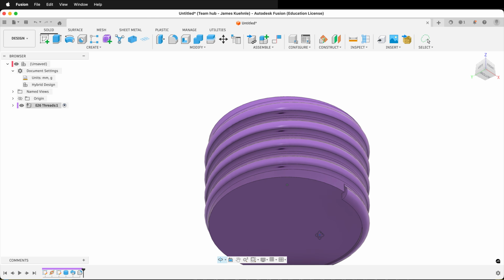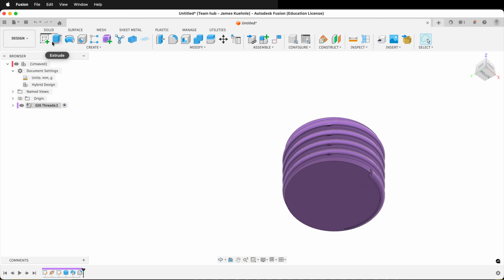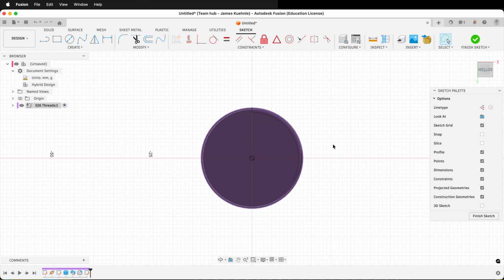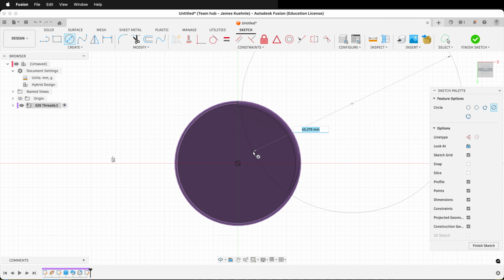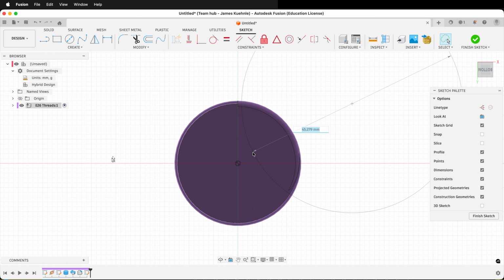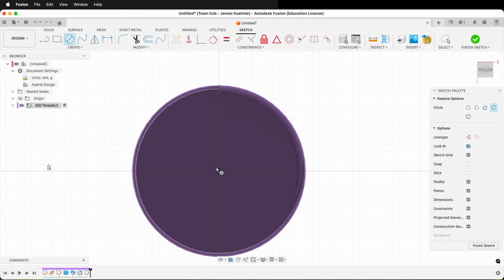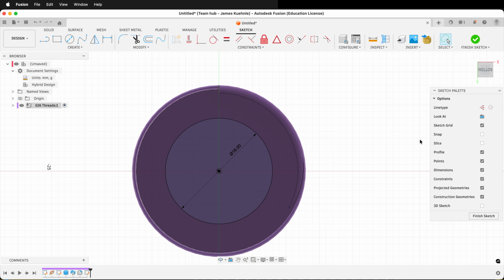On a light bulb, it tapers down to make an electrical contact, and this is a standardized measurement. So we'll create a sketch on the ground plane. Select Sketch, and then the ground plane. Press C for a circle. This bottom part can have a minimum diameter of 15.24 and a maximum diameter of 17.01. So let's make it 16. Press C, select the origin, and type 16 millimeters.